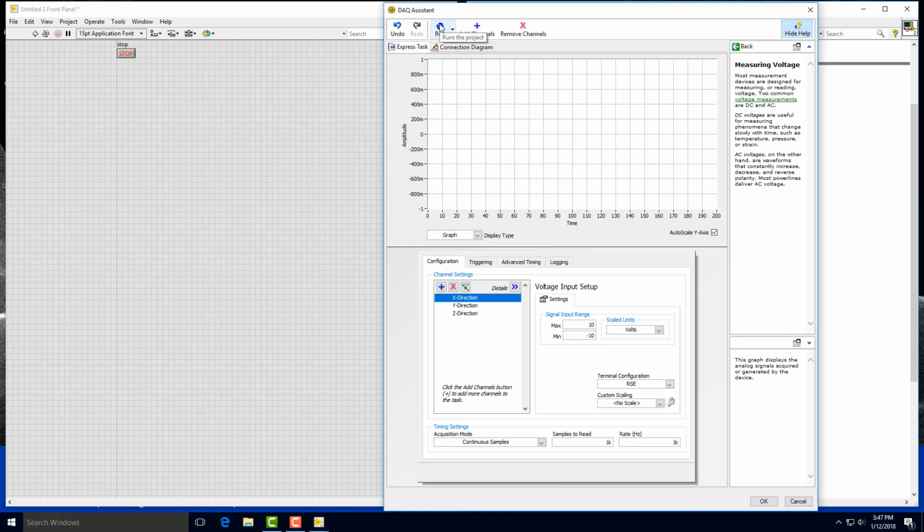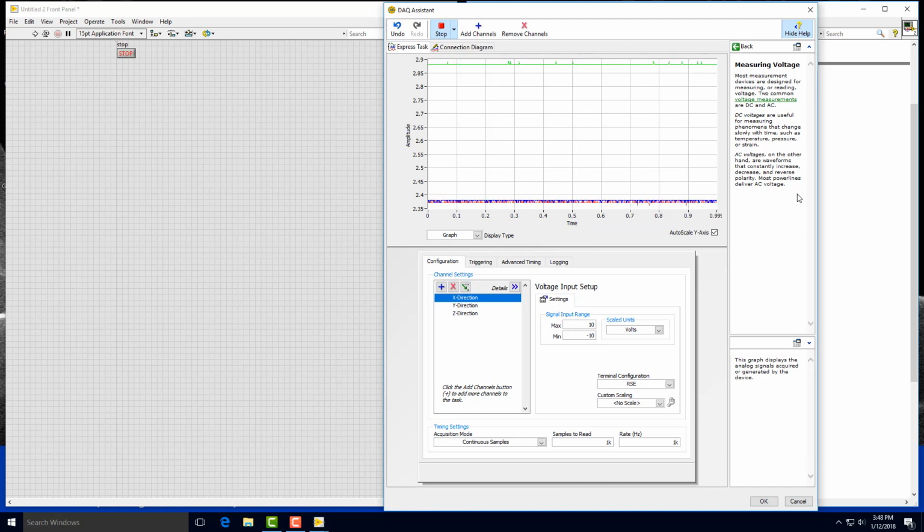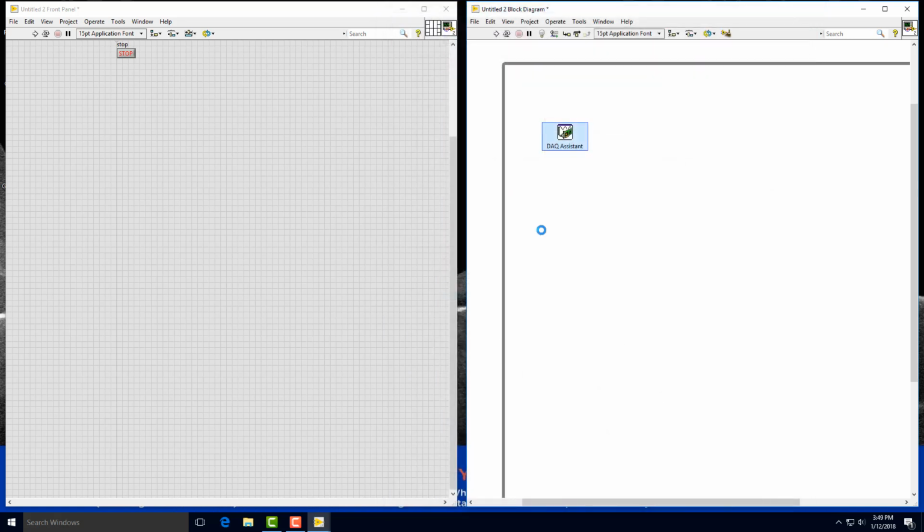And the first thing I do, I want to try to see if my accelerometer is working. I press run, and I see that I have 3 channels. The X and Y directions are about 2.3 volts, and I have the Z direction hanging around 2.7. Go ahead and press OK. I think we are all set up with this. Now this will initialize a little bit, and what it does now is we get a data stream, right, from all 3 channels as the data output.